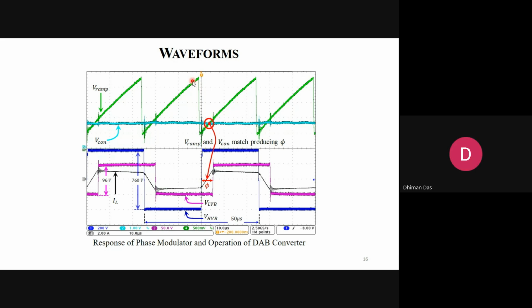If you charge a small capacitor with, say, 1 milliampere, what will be the voltage profile of the capacitor? How will the capacitor voltage look? Okay. So when you charge any capacitor with a constant current source, the voltage will just be the integration of the current injected into the capacitor, right?